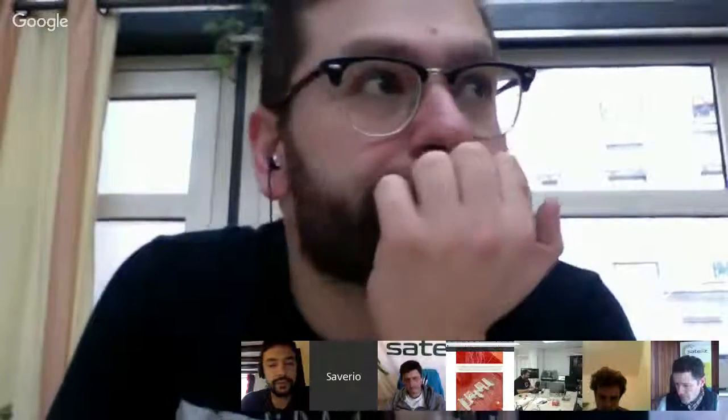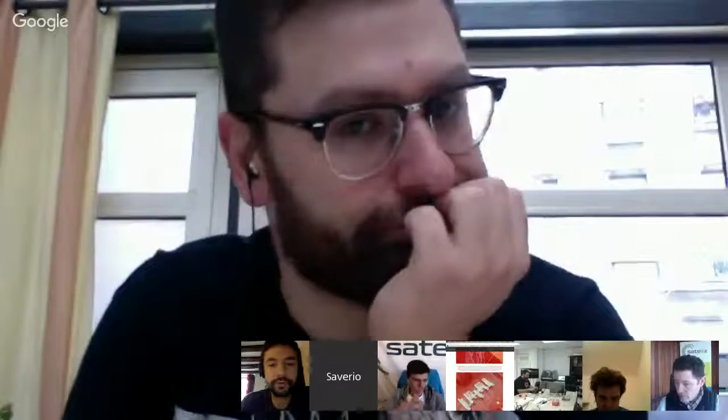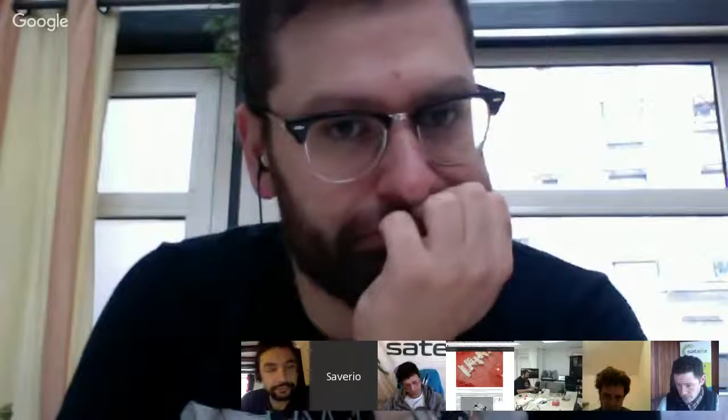I also had a lot of problems with Filaflex because it wasn't extruding well enough. It's quite tricky to put the filament correctly in the nozzle, and secondly, it was quite tricky to set the right temperature and the right parameters to use it correctly. And so the picture you can see here is the result of the test we made. So we had to stop because it was moving too much.